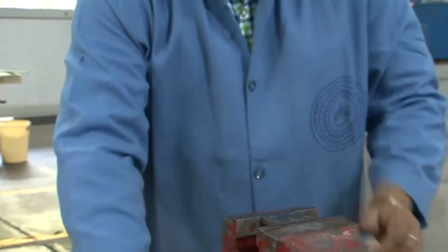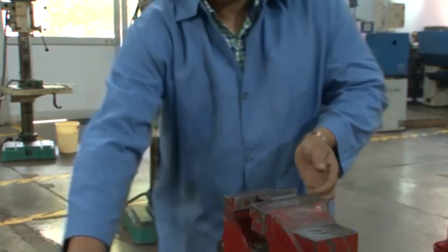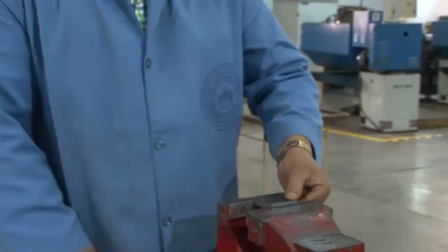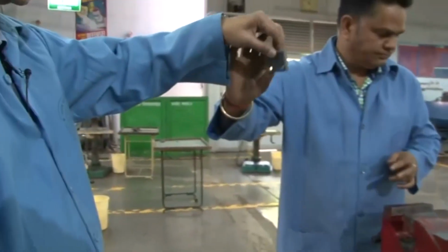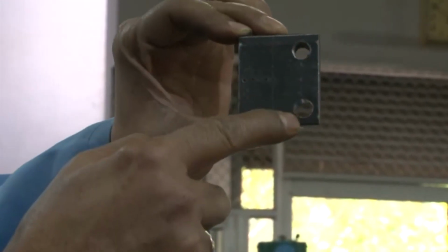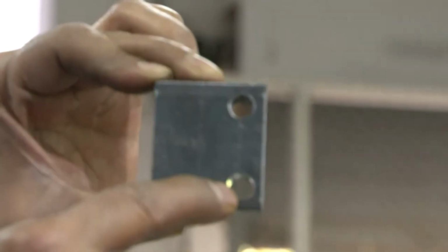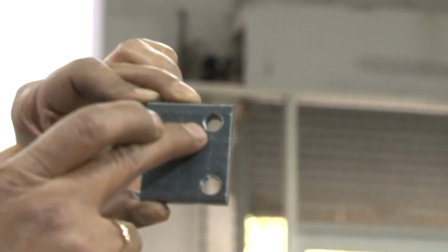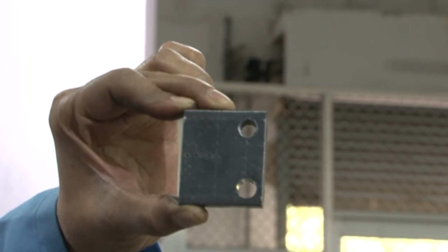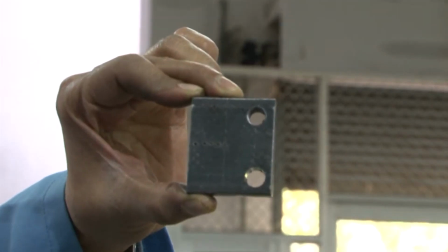So, this is filing, he is filing to remove the burrs from the top from both the sides, otherwise it will disturb the thread coming in. You can see that now the holes are made, and this hole is tapped and this hole is reamed, right. This is a reamed hole without any internal thread as per the drawing, and this is another hole which has an internal thread. You have seen the techniques of how the holes can be drilled, reamed and tapped. That is how the internal thread can be cut.